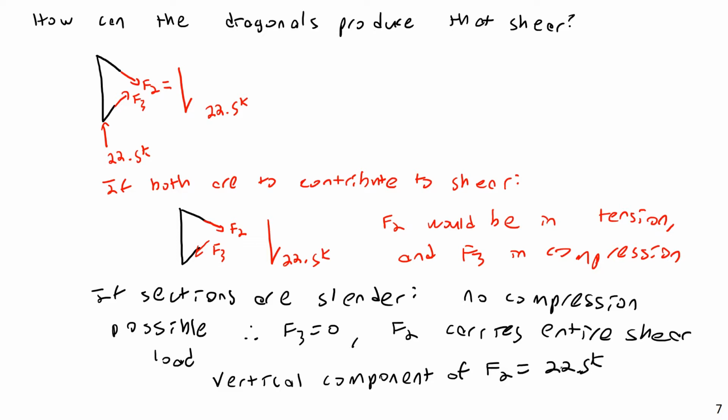And suddenly, based upon that, we have one more known. If we do that across each of the panels, that'll give us 4 knowns, and then we'll be able to have this truss be completely statically determinate.